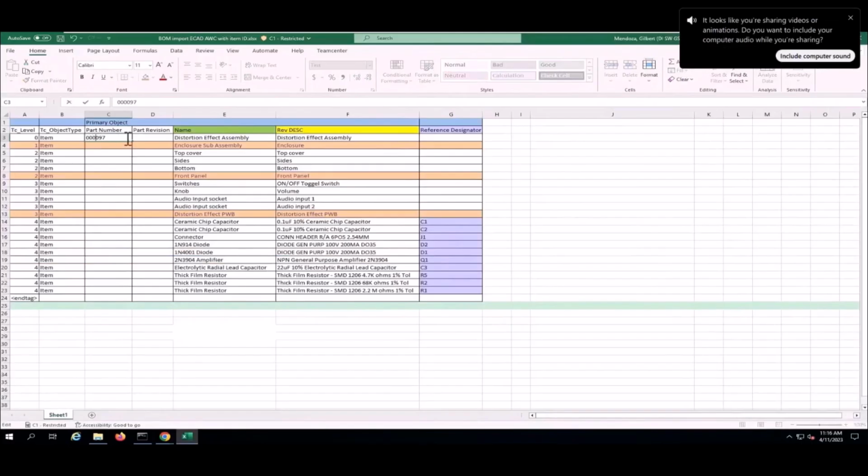And I'm going to use Excel to fill in my part numbers for me. So sometimes you have part numbers that are already filled out. And then you say, well, those part numbers may exist in Teamcenter already. What is it going to do with those? So I'm going to say okay, I'm going to leave it alone, and I'm going to change some of the item IDs just so I can make them unique. So in this use case, I'm going to put in my initials here in the front. I'm going to do this to several different objects as we go through.